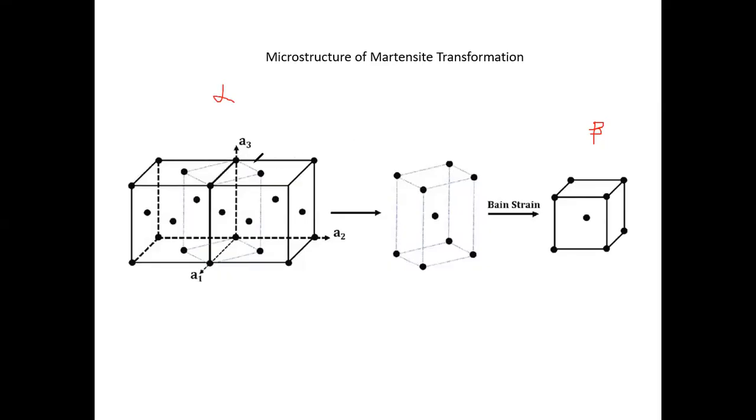Well, the trick here is that this unit cell, which you typically see for FCC as a cube, right, with atoms decorated on the center of the faces and on the vertices, it's just one way. Okay, it's just one of many possible ways to represent the unit cell, or the fundamental repeating structure for you to construct the whole crystal.